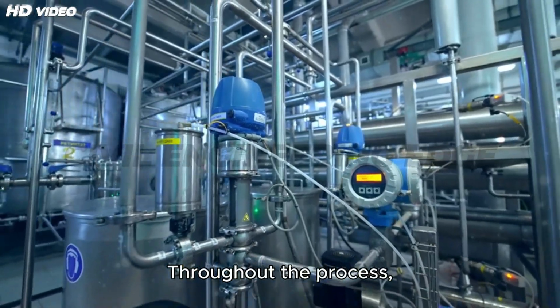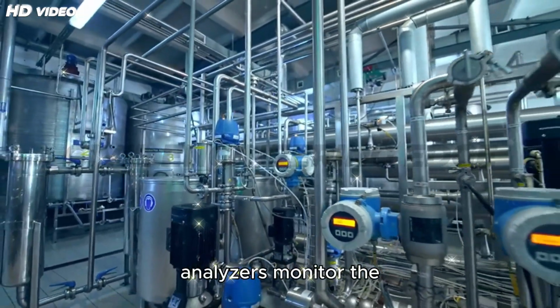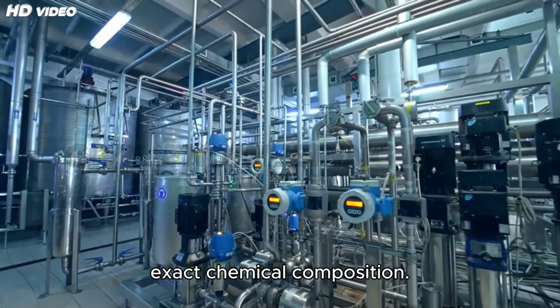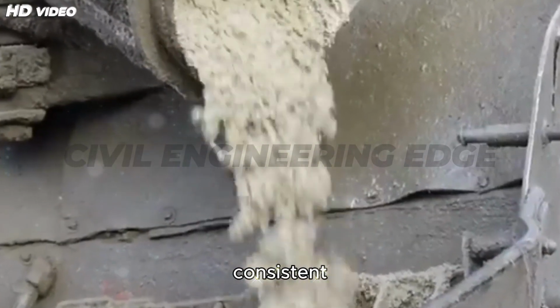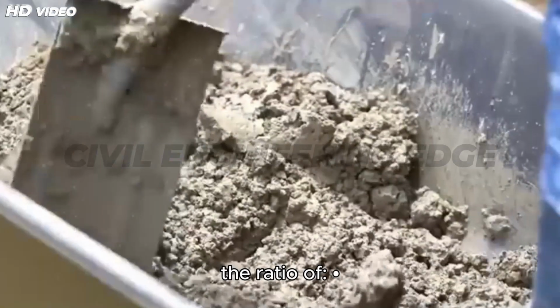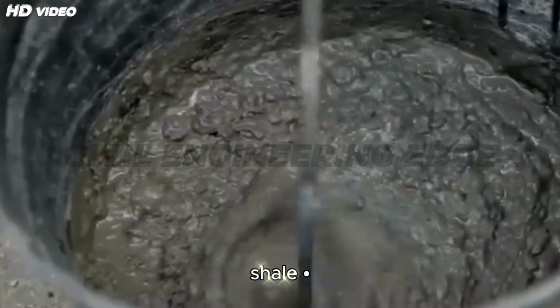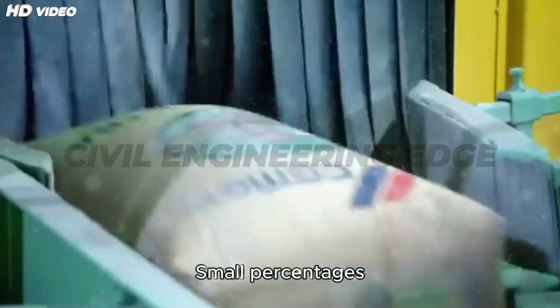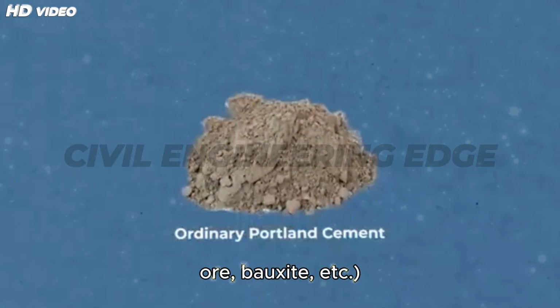Throughout the process, automated weighing systems and online analyzers monitor the exact chemical composition. The goal is to achieve a consistent proportion of raw meal, usually in the ratio of 75 to 80% limestone, 20 to 25% clay or shale, and small percentages of corrective materials, iron or bauxite, etc.